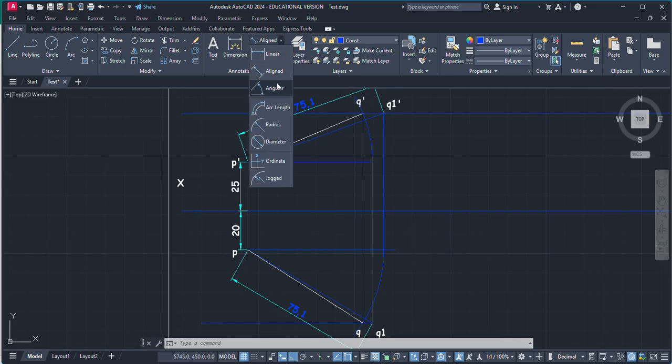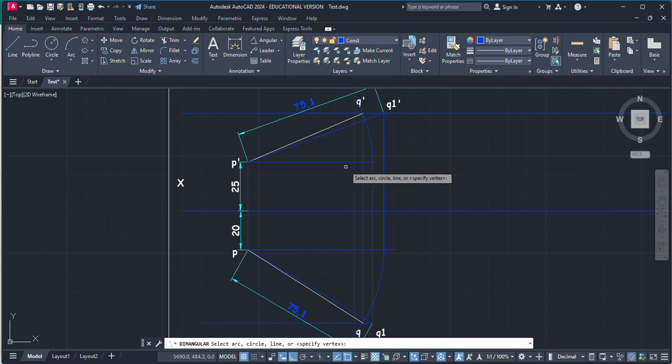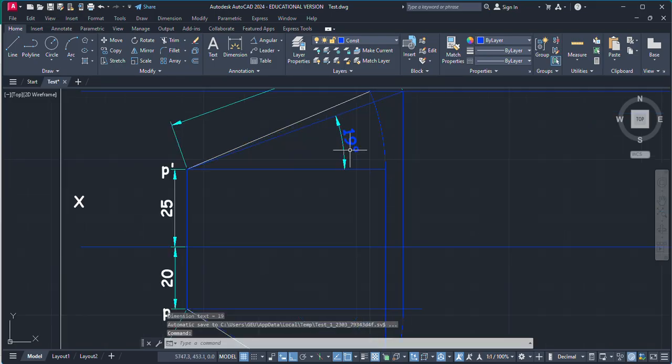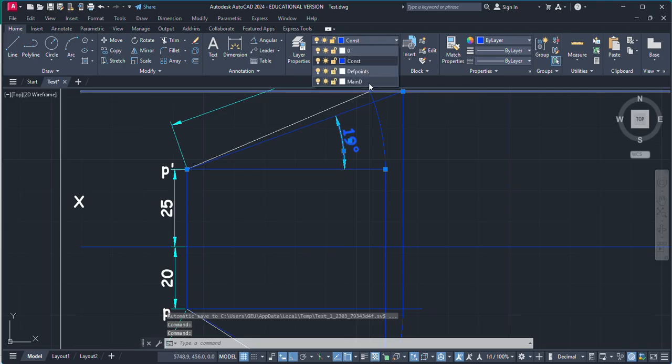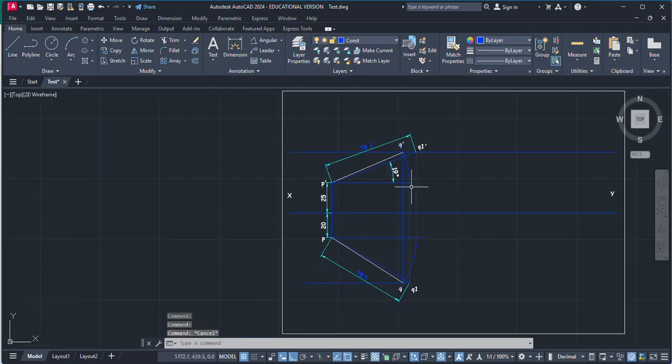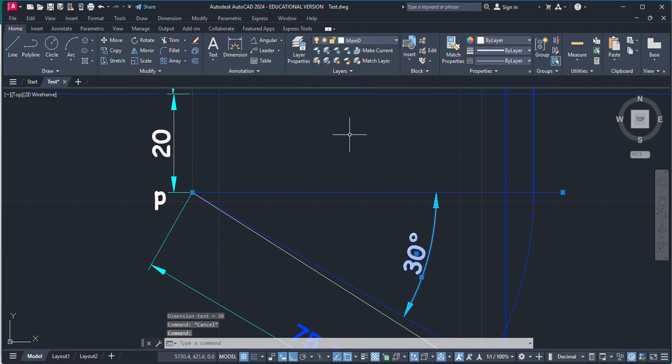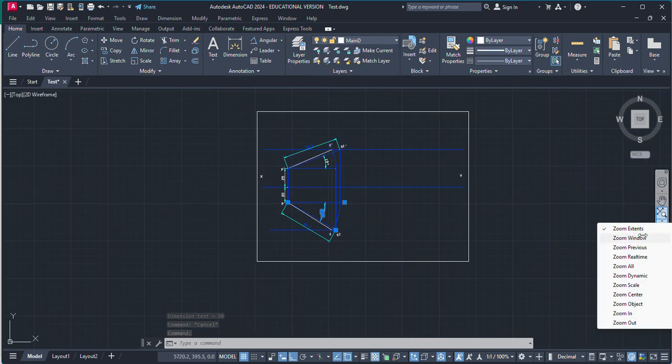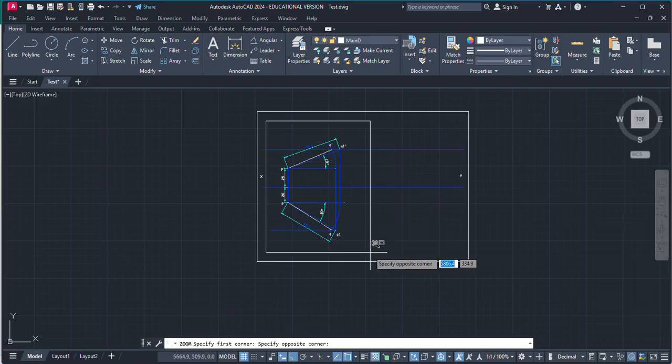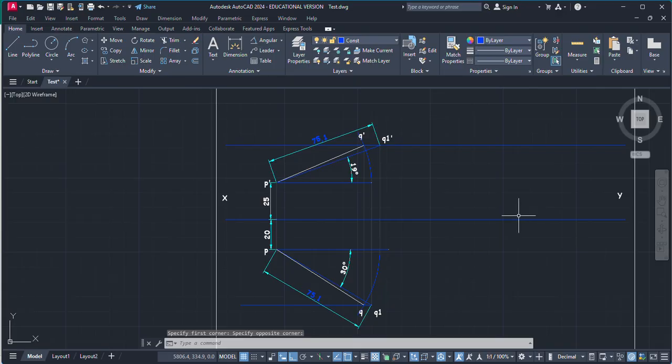Now you have to check the true inclination, the angle made by this true line with the HP. It is asked to find the true inclination with HP. So whatever angle this true line makes with the HP is our answer. So this is our true inclination, which is 19 degrees with HP. You can just check this one also: the true inclination with VP is 30 degrees. Okay, that's it. So this is our projection of the line for this question. That's it.